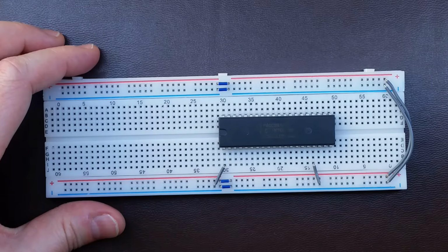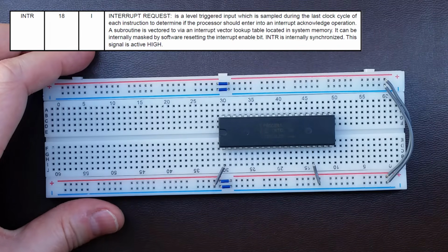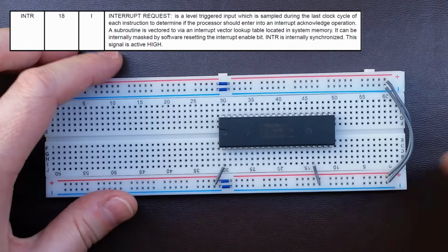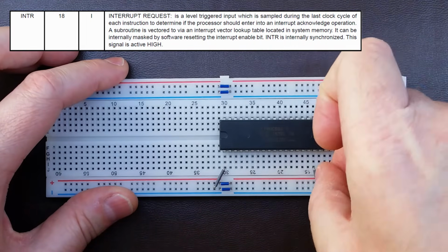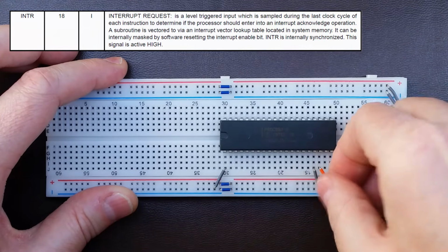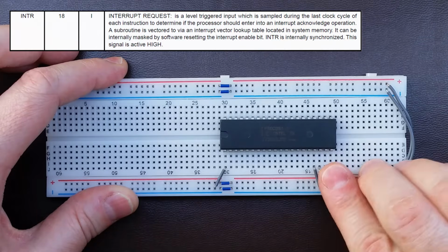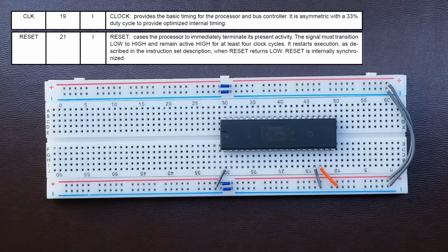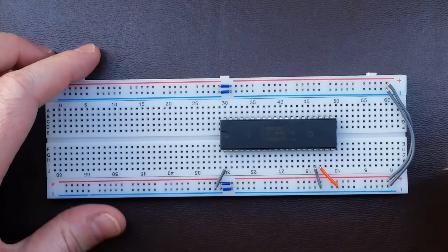Pin 18, INTR or interrupt request. It is active high, so for now we need to connect it to the ground as well. Maybe I'll use that one for a change. Like so. Pin 19, CLK, which is the clock, the CPU's heartbeat. We are going to leave it till last together with pin 21, the reset signal. Pin 20 is another ground.